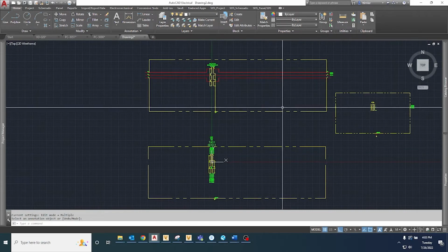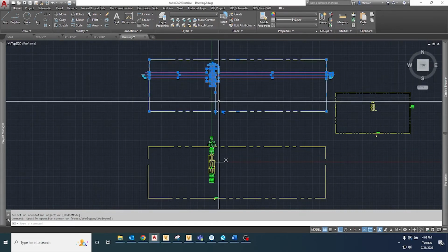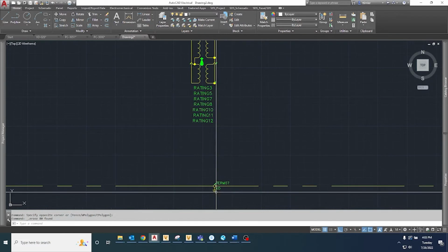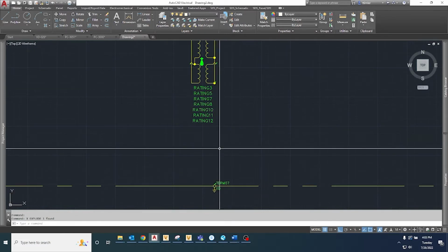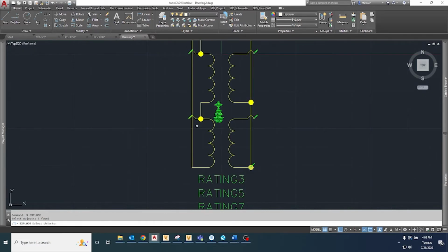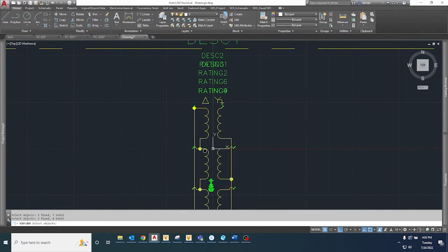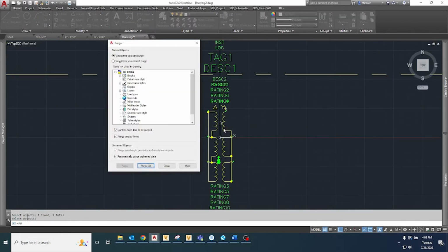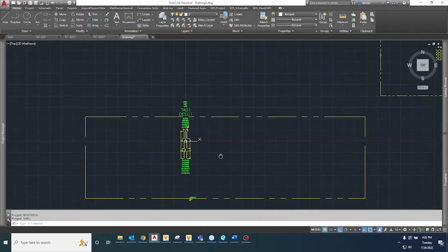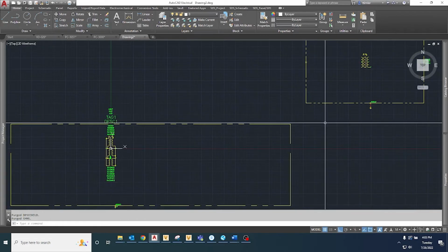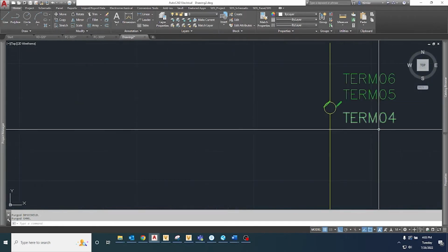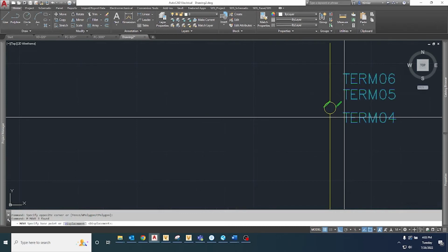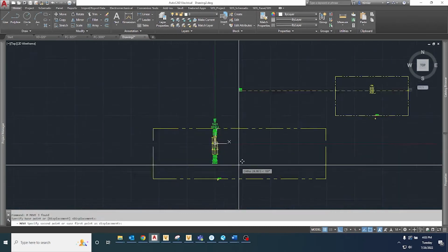I suppose I can clean up this drawing at this point. I want to just go and explode some of these blocks that were in the old AutoCAD block, and then purge the drawing of any of this unnecessary stuff. Like so. The last thing I want to do here is to match up the connection point attributes with their respective term attributes. As I'm doing this, I'm starting to second guess the way I was approaching the build.